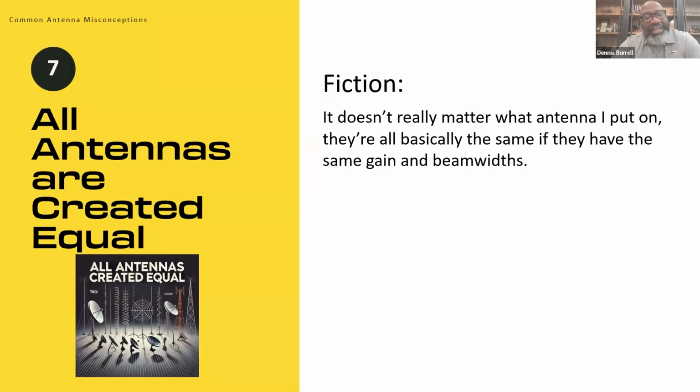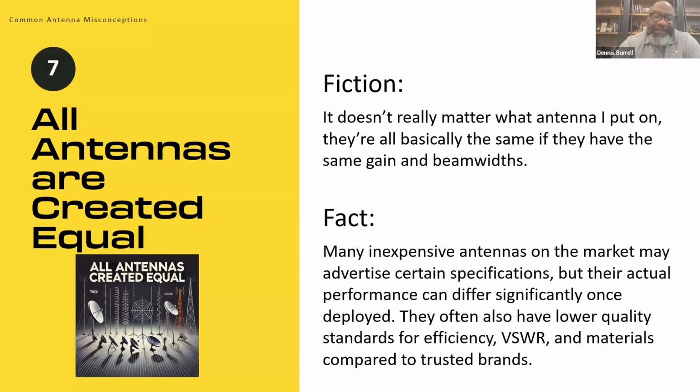All antennas are created equal. It doesn't really matter what antenna I put on, they're all basically the same if they have the same gain and beam widths, which is fiction. The fact is, many inexpensive antennas on the market may advertise certain specifications, but their actual performance can differ significantly once deployed. They often also have lower quality standards for efficiency, VSWR, and materials compared to trusted brands. So quality is a big issue with less expensive antennas.